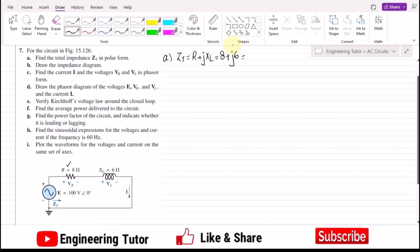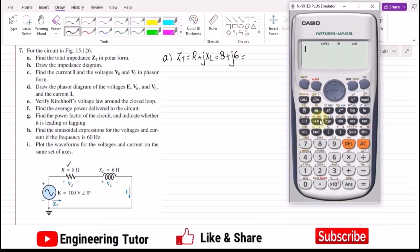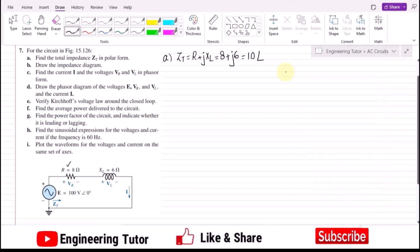Now in order to convert it into the polar, what I have to do, let me use the calculator, and here 8 plus 6 iota, okay. So that is 8, and now in order to convert it into the polar form, what I have to do, I have to write it, and it will be 10, and the angle it has is 36.87 degrees, and that is basically in ohm.